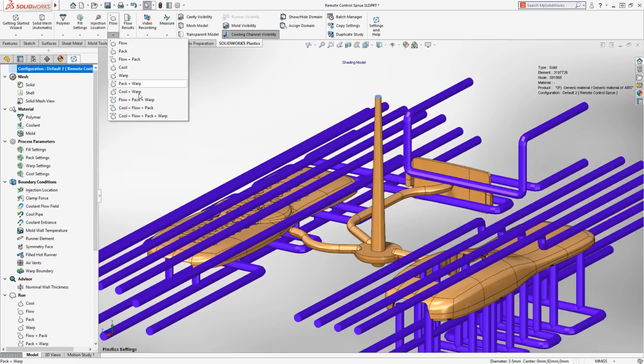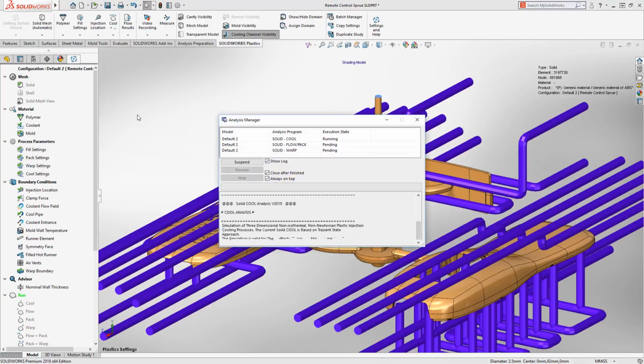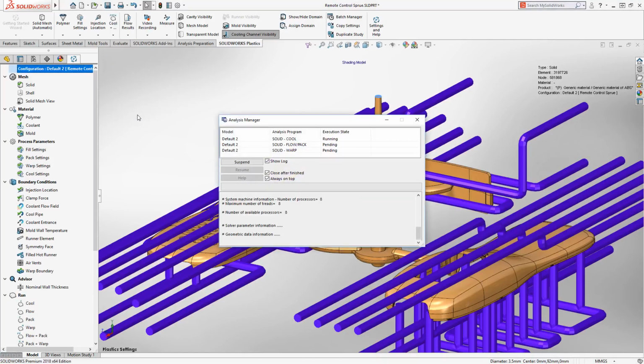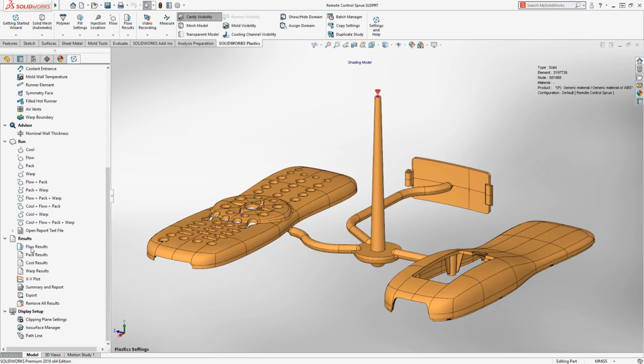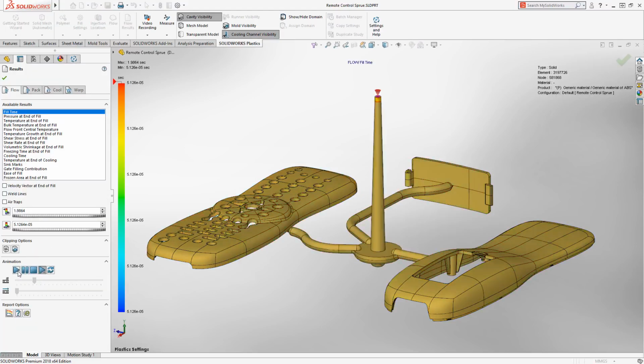Once the simulation of your molded components is finished, you can evaluate the results to determine how those parameters alter your finished plastic injection molding products. In some cases, you're looking for immediate information, such as determining fill time of your cavity. Or more importantly, if your specifications will result in a critical failure, such as a short shot. SolidWorks Plastics helps determine the optimal parameters to determine conditions like these and optimize the overall fill process.